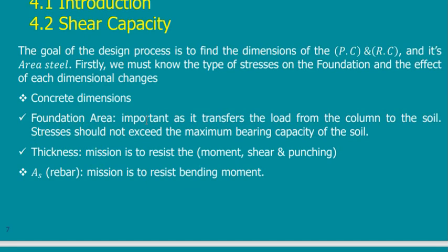By the way, this we have said in our description of how we design the foundation quickly. The first thing we do is to design the area. I get the load divided by the strength of the soil or of the material below to get an area. So this is the foundation area. I should not go less than this area, otherwise the stress will increase. So this is the minimum area that I can use to ensure that the bearing capacity of the soil is not exceeded.